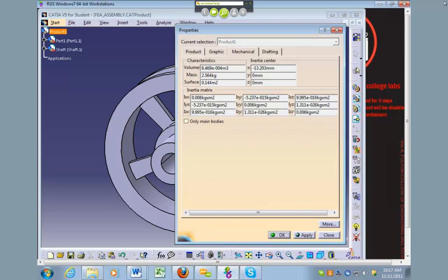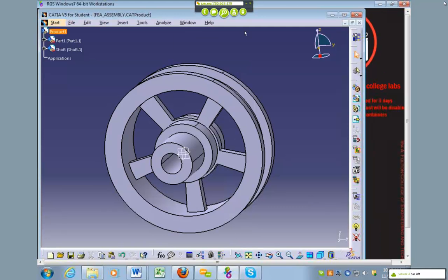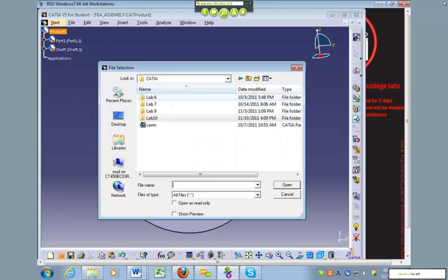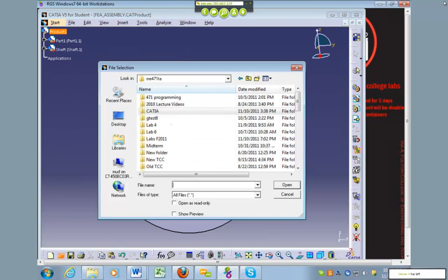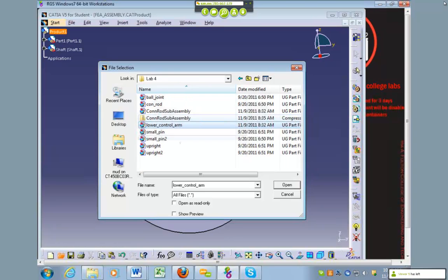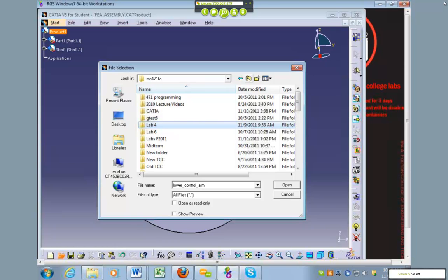But if you just think about if you were the designer of the hood of a car and the structural part that goes under the hood, the webbing that goes under there, what you want to do is try and move the center of gravity of that hood as far back towards the springs as you possibly can to make it so that it's lighter to lift up.